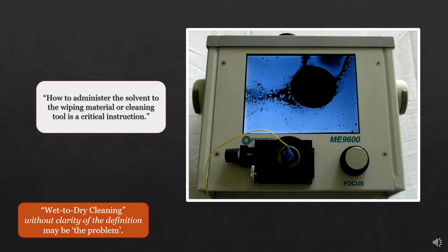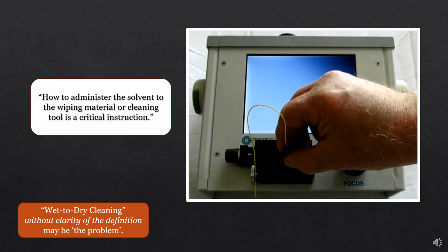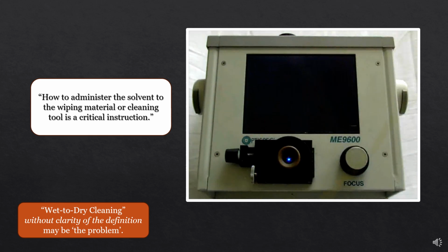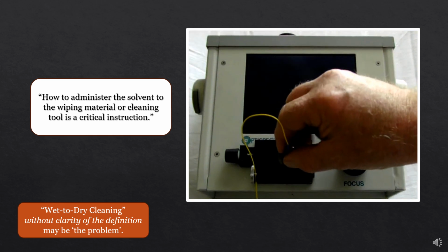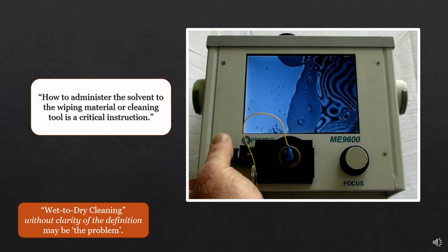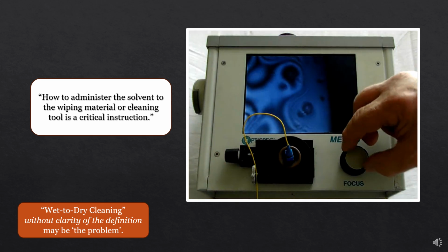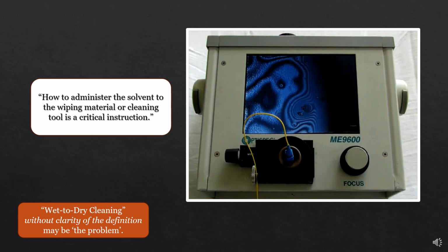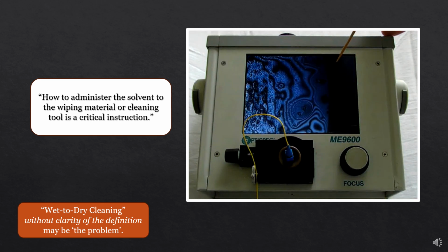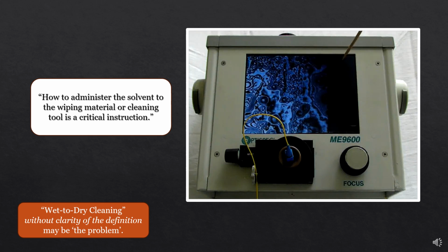We take the end face either through a wiper, or maybe we've pumped solvent into a lint-free wiper, and we simply draw the end face through this IPA. Might do a straight line, might do a figure eight. There's no definition. What we're seeing here is flooding, and that's pretty obvious. But as we go to dry it, we find that we might get it dry within the field of view.